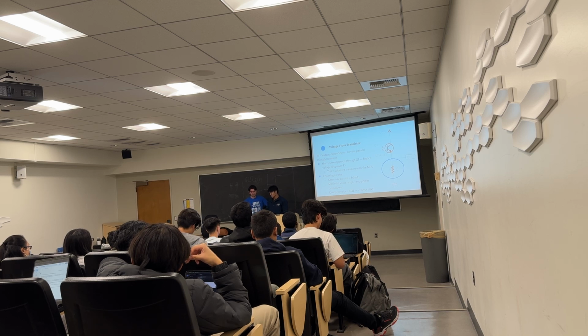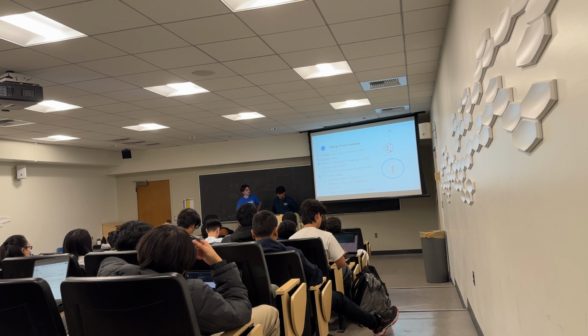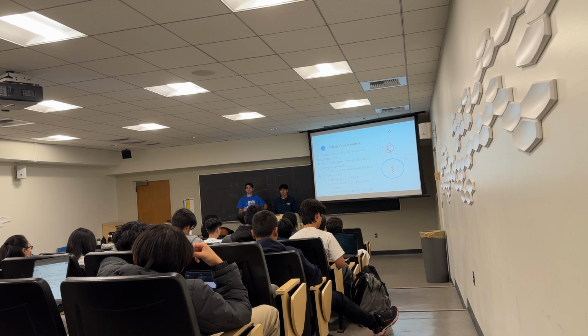The choosing-the-value part, I'm not going to go through it exactly, but on the bottom it says choose a value greater than 65 ohms, and then it makes a seemingly arbitrary jump to 1.8 kilo ohms. That's what I said earlier: we can tweak these values, and the functionality usually doesn't change.